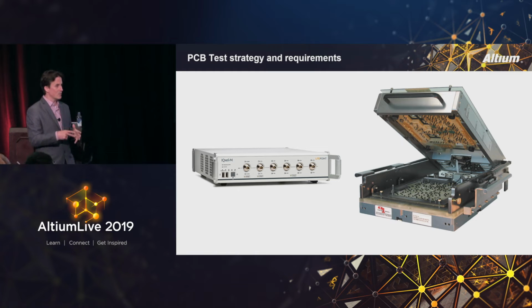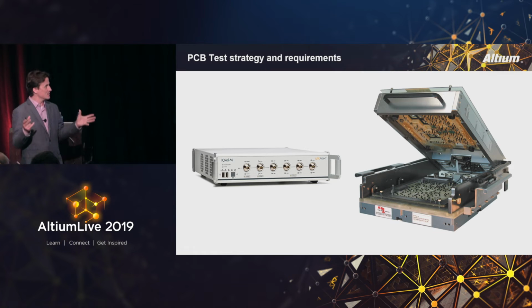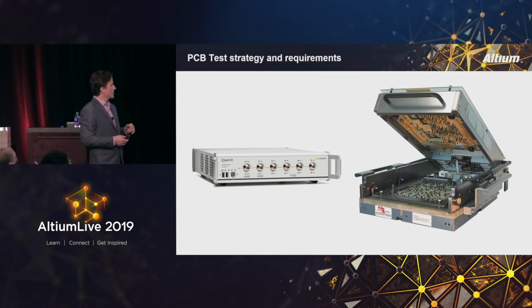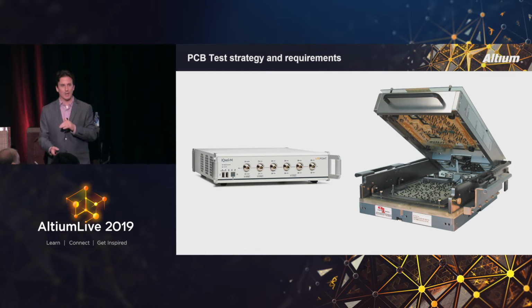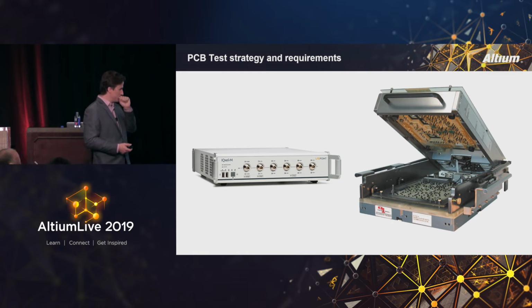Because if you wait until final assembly, then you're throwing out everything when that RF radio does not work as intended. We have used the LitePoint tester from LitePoint, and we have made provisions to do the programming of the PCB and the RF testing in one step in an RF box. So this is an important design consideration.